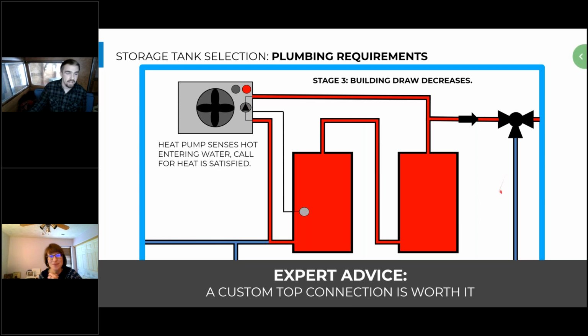Yeah, so that's a great question, and there are different ways to handle that. The short answer is yes, it does cause a high entering water temperature at the end of run if you signal the heat pumps to turn off once these storage tanks are completely full. So depending on the limitation of the heat pump water heater, you might turn them off when there's still a little bit of cold water left in this tank.